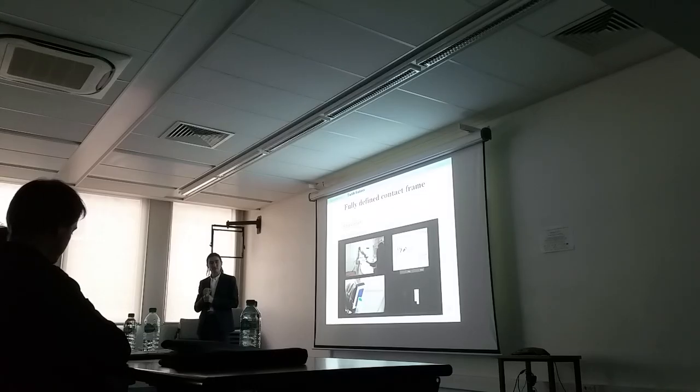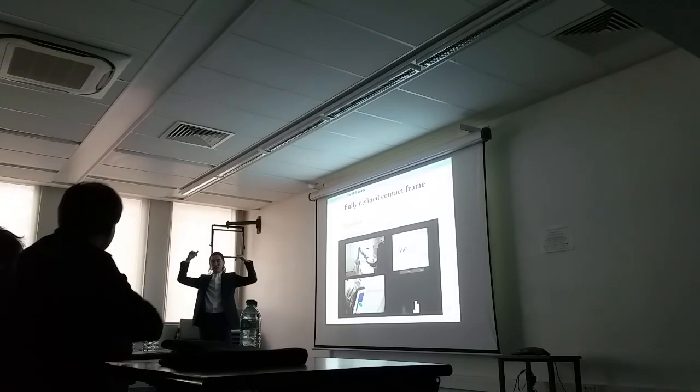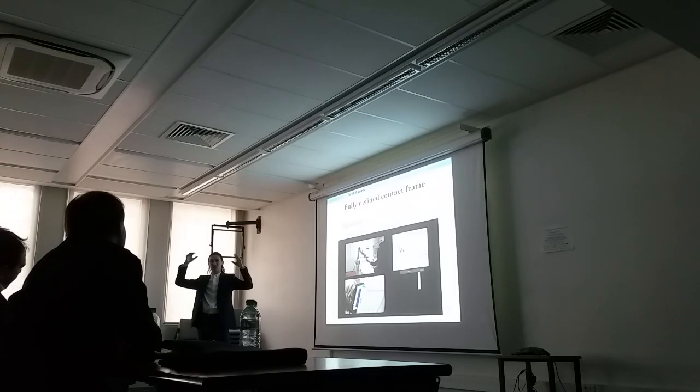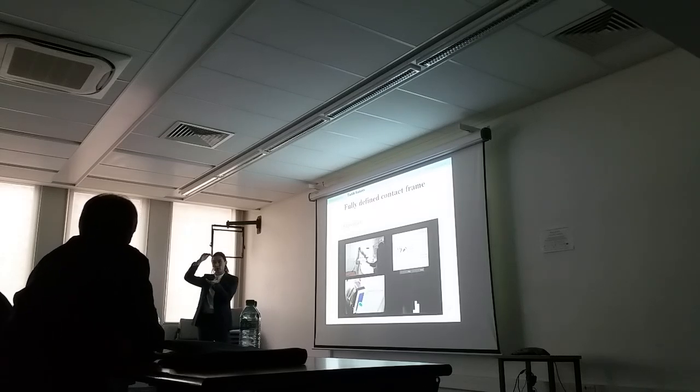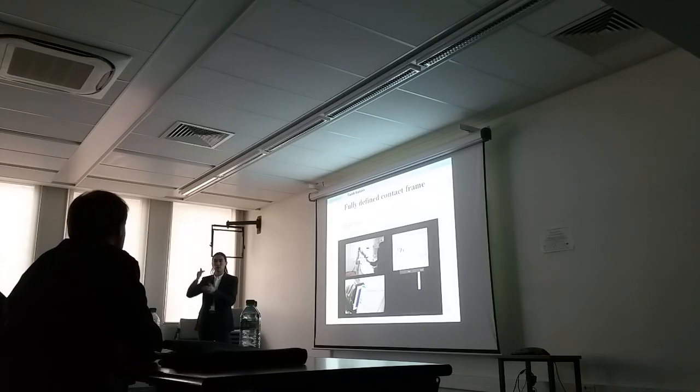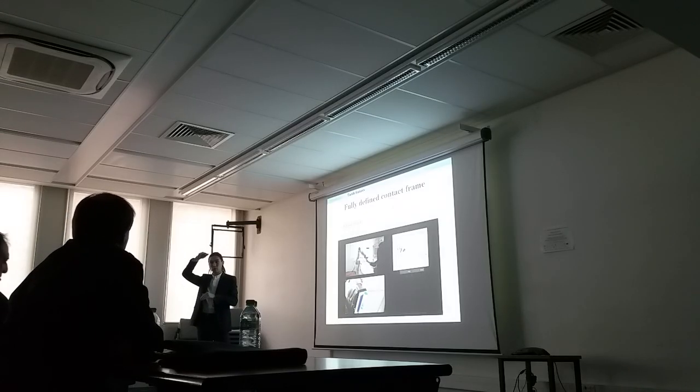It's like when there is a water tank with a non-linear shape, and we want to control the level of the water inside. If our controller is fast enough, we don't have to model all the shape, all the volume of the water inside the tank to control. We can just control the level where we measure it without knowing the model, if the controller bandwidth is high.